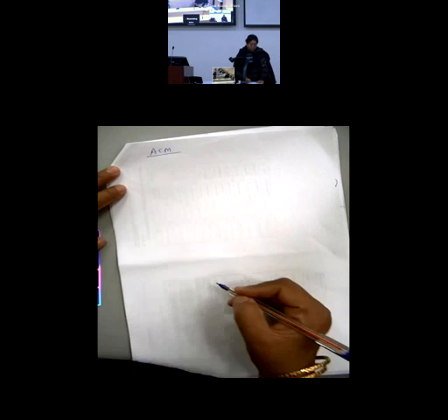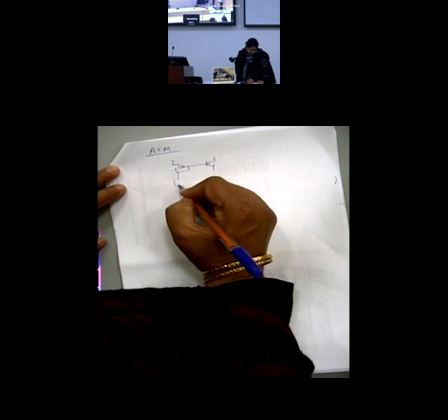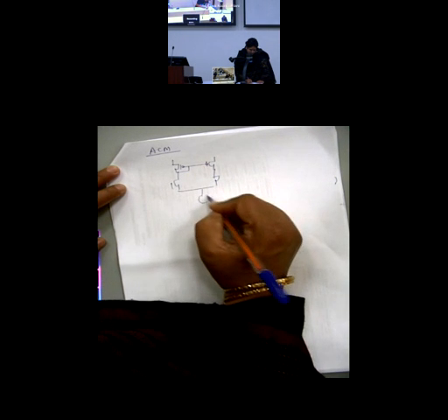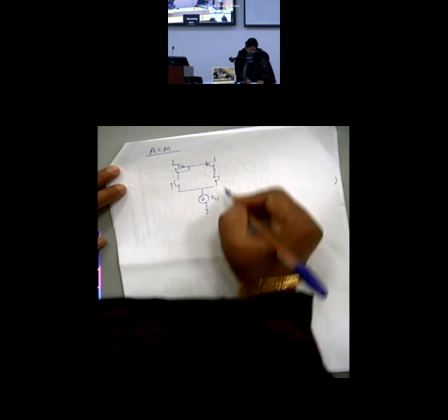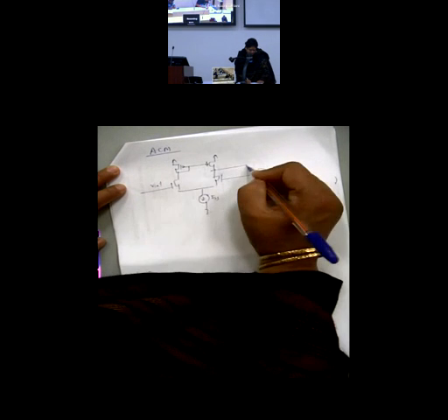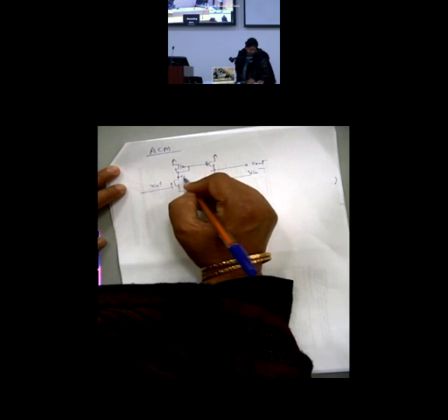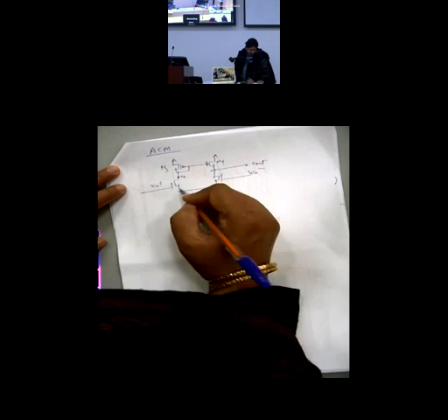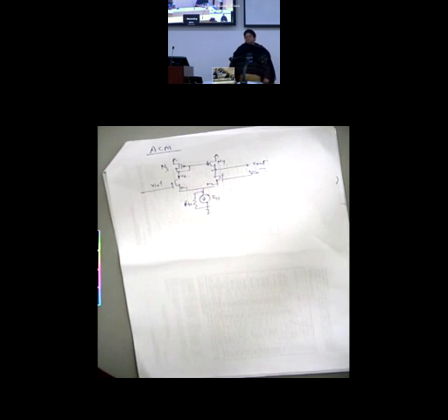So can you do common mode operation? Same analysis, current mirror active load. But now we are doing ACM and finding out CMRR. Again, remember you have a current mirror load structure of a differential pair. This is ISS grounded, V in minus, V in plus, VDD. This is V out, and this node is Vx. Say M3, M4, M1, M2, and you have an impedance RSS. So can you find out the ACM?